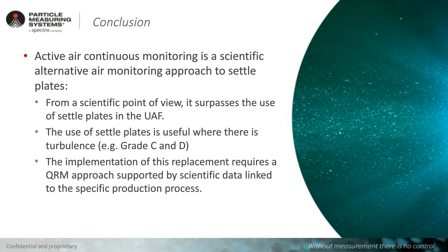But in critical areas, the data generated by settle plates is really questionable and not validatable, and especially it is not actionable data because you simply cannot trust what is coming out. As a consequence, people will be considering at this moment of time, now that we have a new era of regulation and understanding of pharmaceutical manufacturing, to implement active air sampling by replacing settle plates with active air sampling.